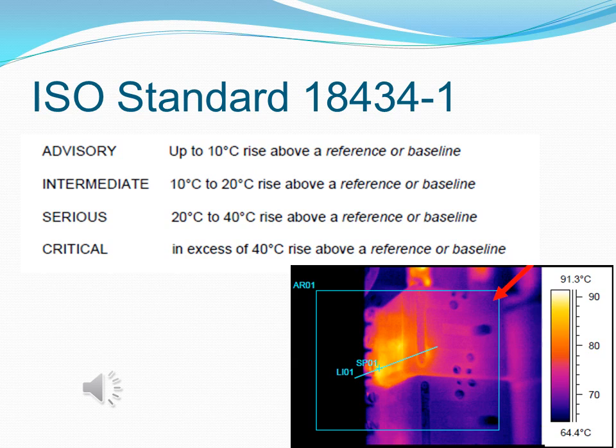Above 40 degrees centigrade rise from the ambient temperature, it's classed as a critical problem. So the problem pictured here, what first looks like a 26-degree rise as a serious problem, is really a critical problem according to this standard. Serious can be a common term, it can be a bit ambiguous, but critical is a critical issue that needs to be dealt with quickly.